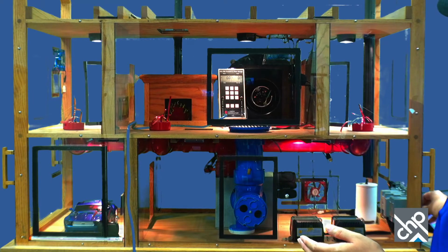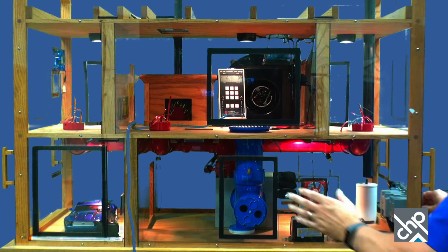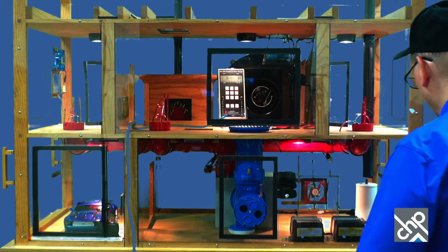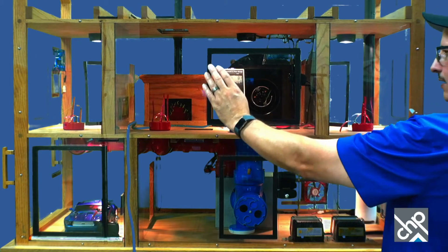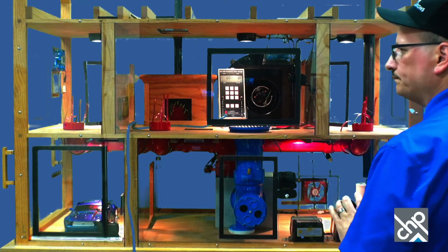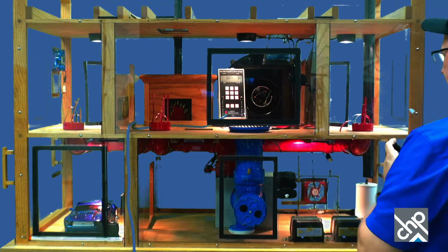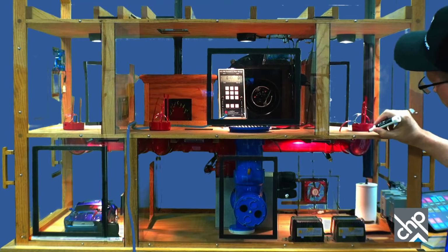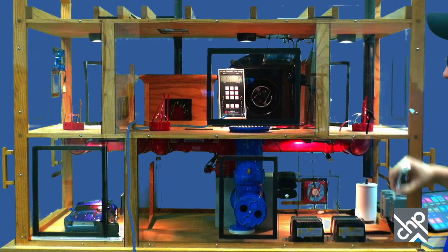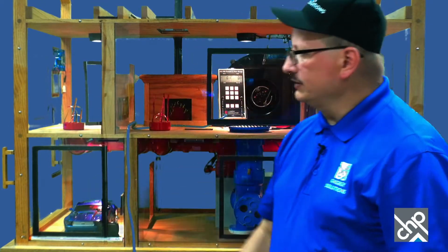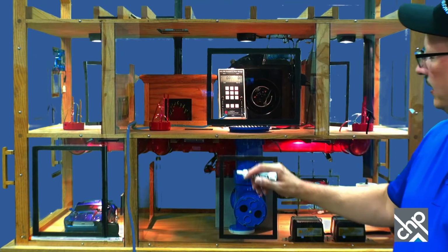So let's just turn on some things. The first thing I'm going to do is turn on the air handler fan, which is going to be my fan here. I've got a little furnace fan in here. And when I do that, you'll see the streamers come on. I believe I showed you that before. The smoke was going out, and then you have a return, the air's coming back. And then the doors are open. So essentially, you've got air coming out. This is what they call a central return system. They've got air coming out in every bedroom, because there's a supply in every room. And then right here's the supply.